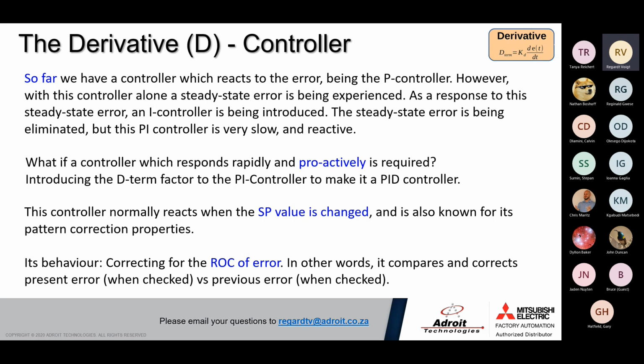Another element that can cause a very high D response is if there's an instantaneous error being induced in the plant process. Let's say a pipe burst on the tank level, or if it's a very small tank, then your D term will play a huge role to try and reduce the error to 0.